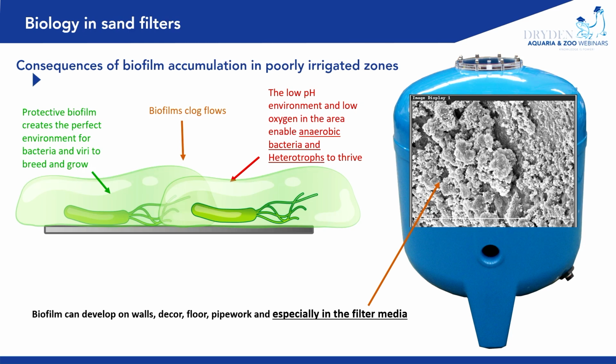So initially it's good because it starts to help in filtration performance, but once that biological fouling becomes saturated throughout your whole media, it is very negative and results in all of the previous clumping problems that we've been discussing, reduction of pH and reduction of DO, and creating anaerobic environments. And despite the forced flow of water through a sand filter, it is just not enough to feed the oxygen demand of nitrifying bacteria, it's better that that happens somewhere else.